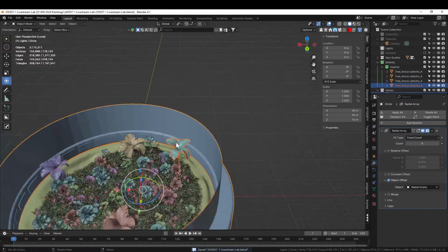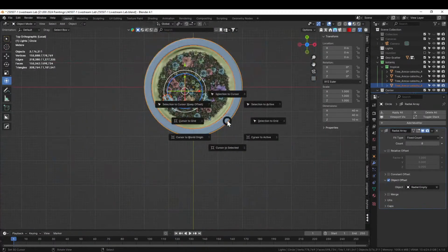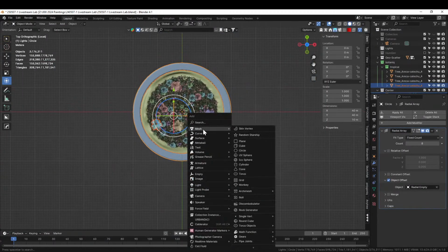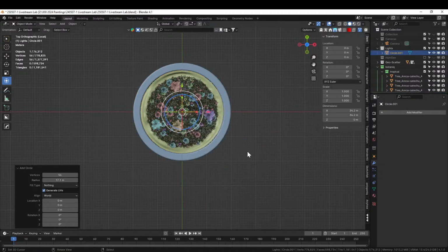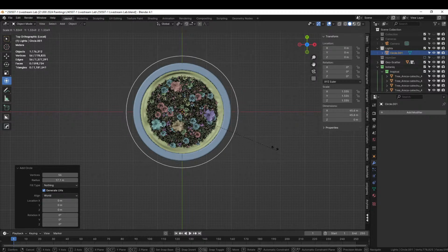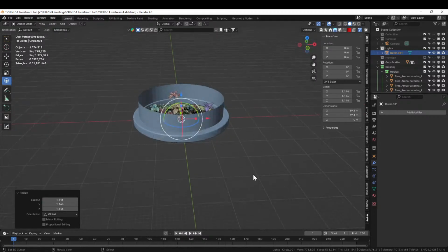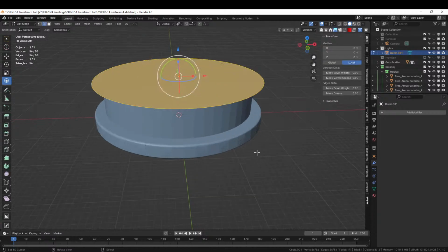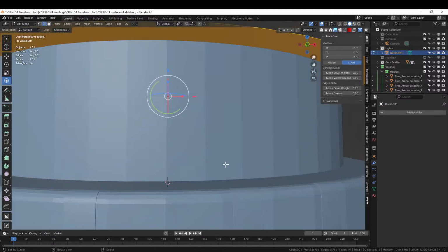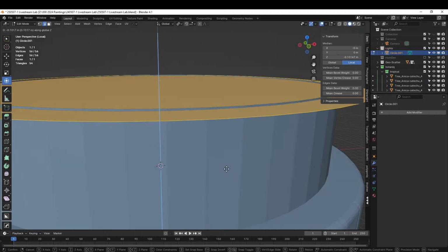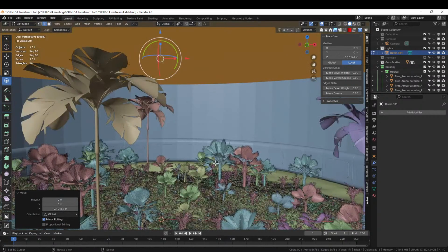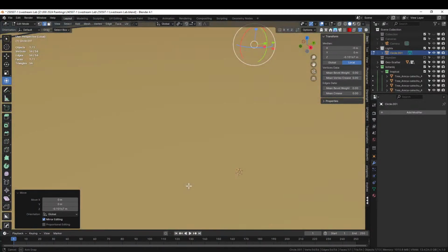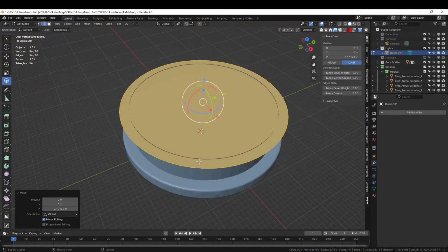Then we should be able to 7, Shift A, mesh, circle, scale. And we're actually good before. GZ. Control A, rotation scale. Fill it. And there we go. And this, we should be able to, again, let's assign it to shiny,